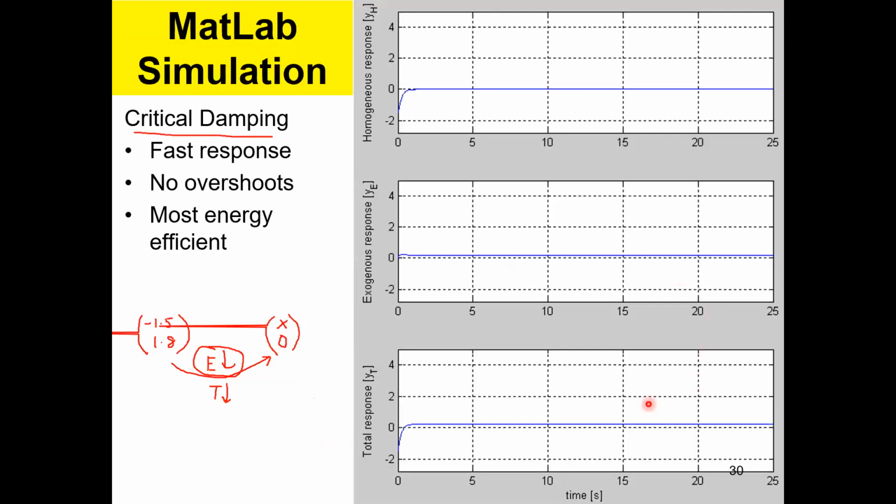About 2 millimeters. Then you come over here and check that out. This is about 2 millimeters. This is 2 centimeters, and this is about 2 millimeters, right? So I think it's very obvious that you don't want this kind of shock absorber. When you jump on it, it only squeezes 2 millimeters. So it looks like you jumped on a piece of rock. It doesn't move. Okay. So you want the shock absorber to move initially, otherwise, it will be really painful experience, right? But this oscillation should not last long. In few seconds, it has to decay. Okay, so that is the kind of performance you need here.